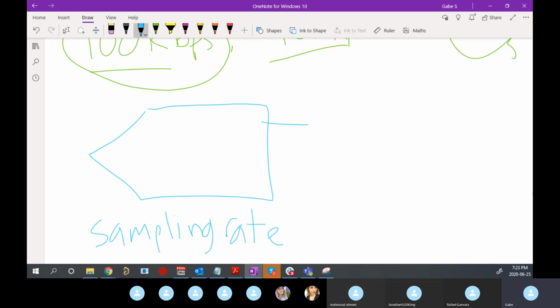You'll see most ADCs come out with SPI, just because it's much faster than I2C. Like if you look on DigiKey, most of them are SPI. You'll see some I2C, but by nature they won't be as fast. So if you're looking for speed, SPI is the way to go. And personally, I like it because it's much easier to work with.